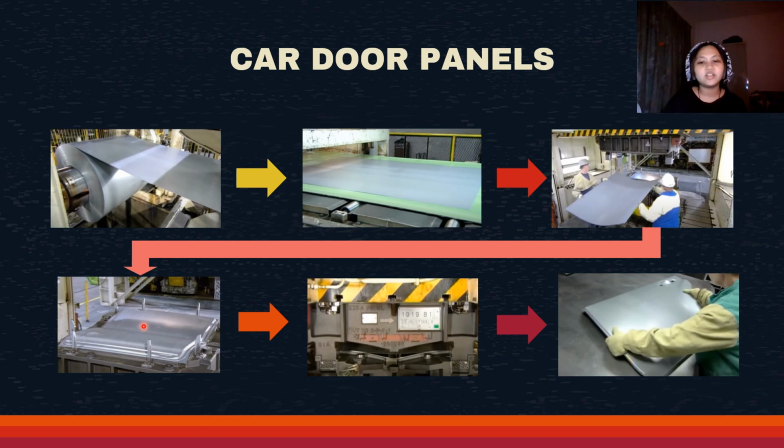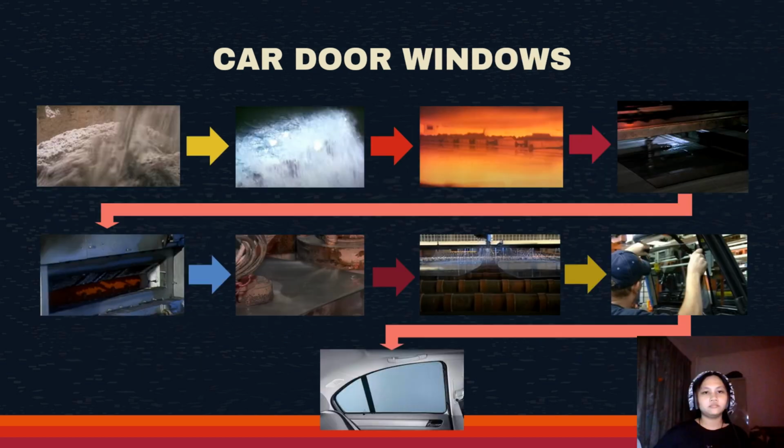In the production line, the main press churns out the car doors. An automated device with mechanical fingers then grips the newly shaped steel and transfers it into a punch cutter machine. The punch cutter machine separates the two doors and trims the excess metal from the edges. Finally, a handler inspects the outer door panel for bumps, dents, or scratches.